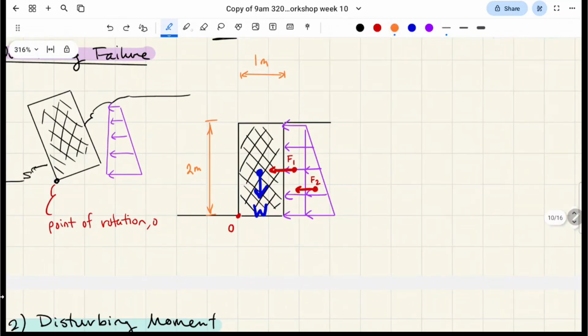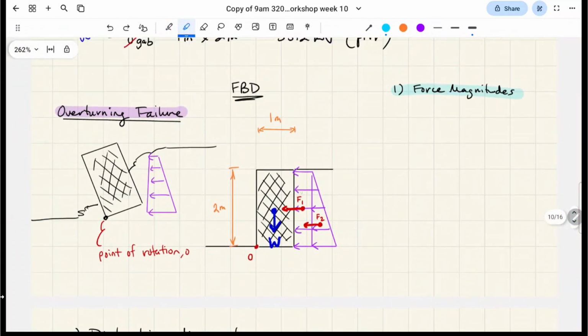The lever arm, let's just do a little quick 1300 recap. Let's talk about W first. So W is the weight force, right, of our gravity wall. What I've highlighted in blue is the line of action. So the line of action spans infinitely in both directions from that arrow, right?